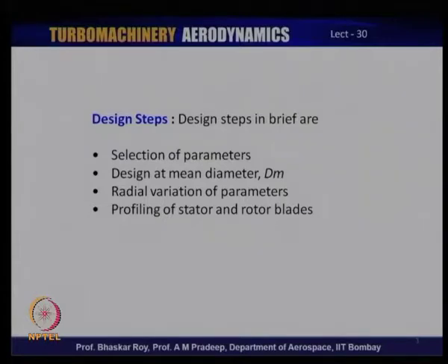So, the radial variation is normally guided by one of the laws of three-dimensional blade design. The primary one, which everybody remembers, is the free vortex law, but as we have discussed before in one of the lectures earlier, in axial turbine design, free vortex law is not the most popular law. There are other laws which are more popular for axial turbine design, and we will have a look at some of those again in today's lecture.